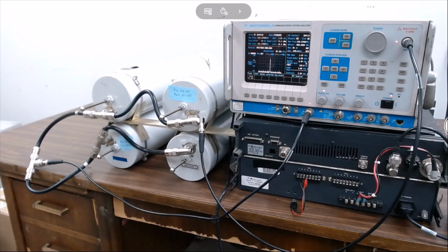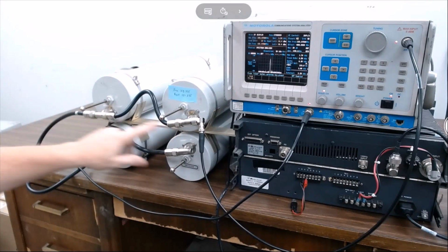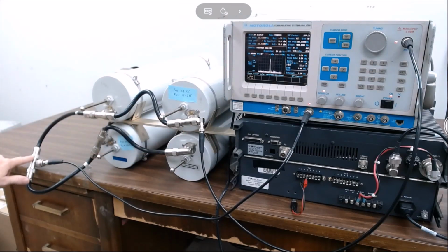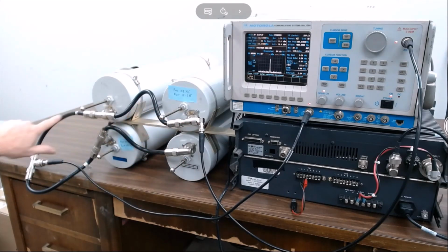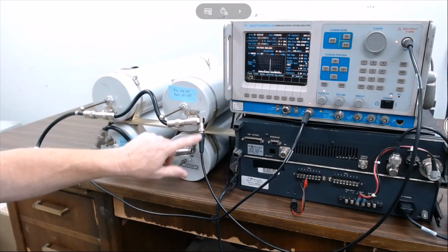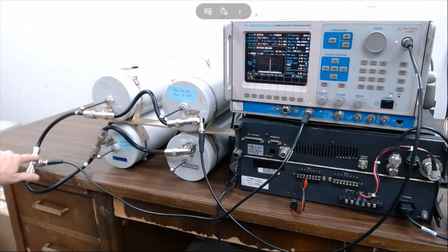Okay, on our next test, we're going to be testing the duplexer, and basically we're going to be measuring the signal when we inject a signal here that's on frequency, how much loss we get going through this side of the duplexer, and we want to have it under 2 dB so that the correct signal coming through here gets to pass through with minimum attenuation. And then we're going to put in the reject frequency and confirm that it blocks just about all of it out from getting through that way. So we're looking at a pass and a reject scenario here.